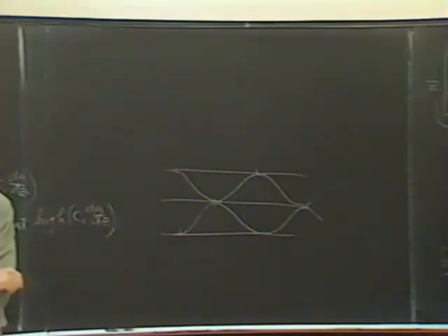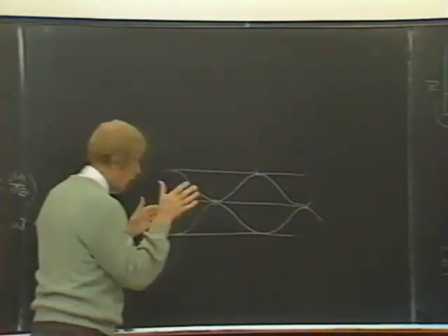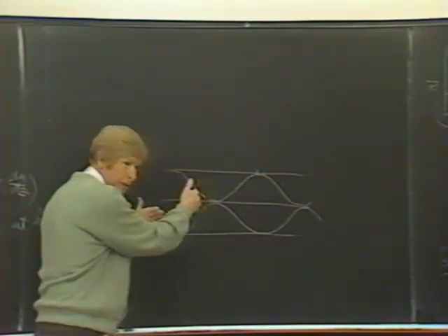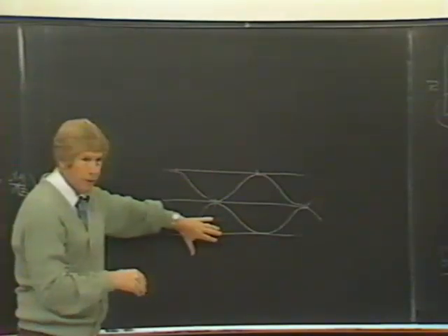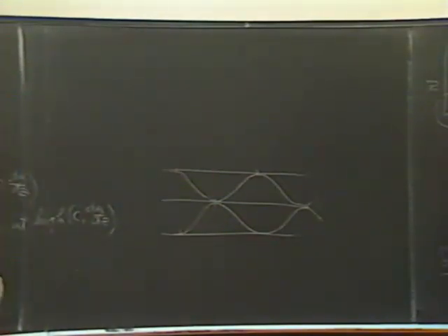So we can substitute for settling velocity in this relationship and have dM/dt equals minus our constant times C to the 7/3 now, times 1 minus tau W over tau critical. So we have now our deposition rate is proportional to the concentration to something more than the square.